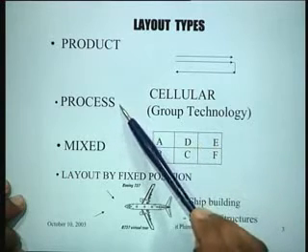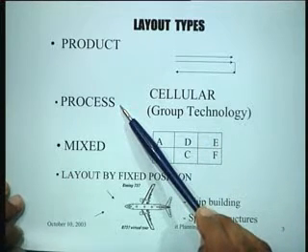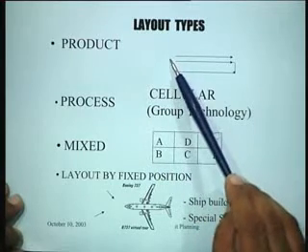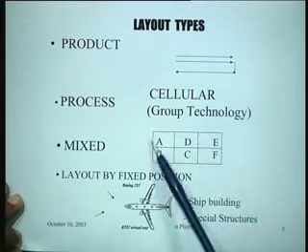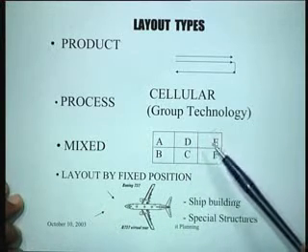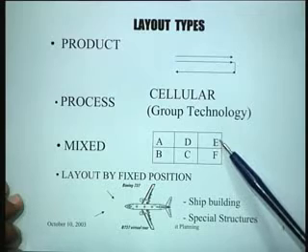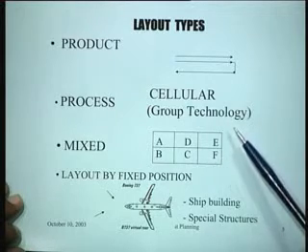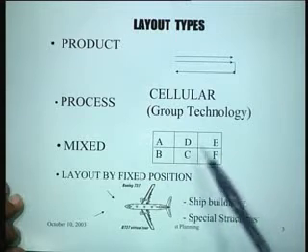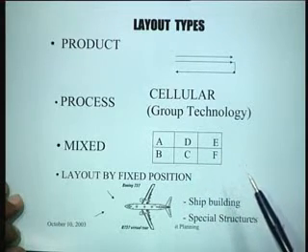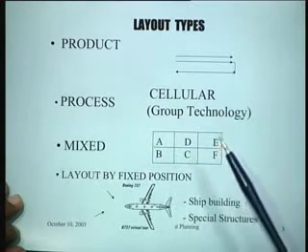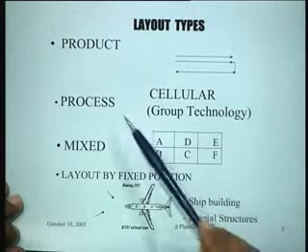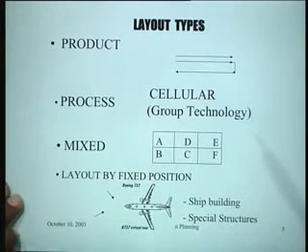So the major advantage of this type of layout is the product variety that it can handle, unlike the product layout which typically handles a single type of product. So you can make a variety of products in this particular layout, and of course, what will be the major problem here? The major problem will obviously be large number of products moving here and there. So there will be a lot of confusion in terms of movement. There will be a lot of delays as products wait and move to different departments. Therefore, the production times generally tend to be large in such situations.